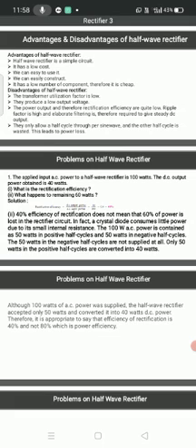Simply, when the diode is in forward bias condition, it conducts. When the diode is in reverse bias condition, it blocks. So here the diode is forward biased in only one half cycle, and in the remaining half cycle it is reverse biased. Only in the forward bias condition will it allow the flow of electric current or voltage. So it produces a low output voltage.